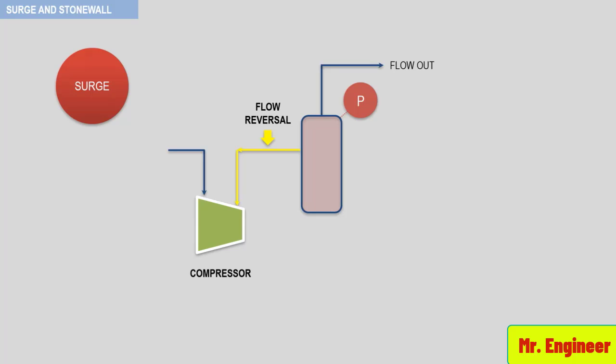Remember that these cycles can occur as rapidly as 6 times per second. This action produces large amounts of energy, which are absorbed by the mechanical components of the compressor, and can result in a significant amount of temperature increase inside the compressor. Think of it this way: the gas moves back and forth in the compressor 6 times per second without being cooled, so temperature increases can be very rapid, and thermal expansion during surge can cause major damage to your compressor.